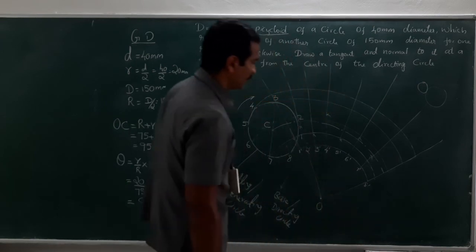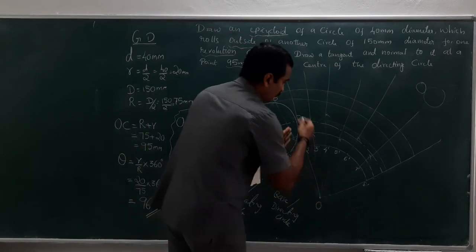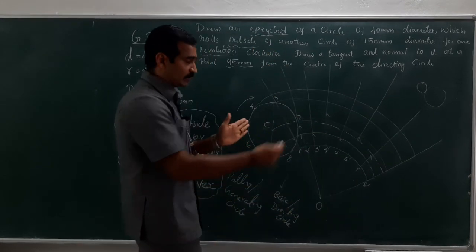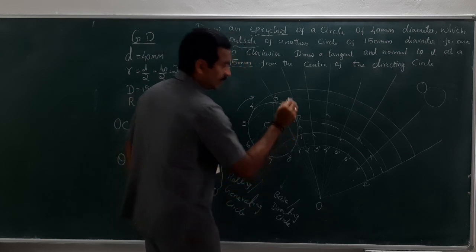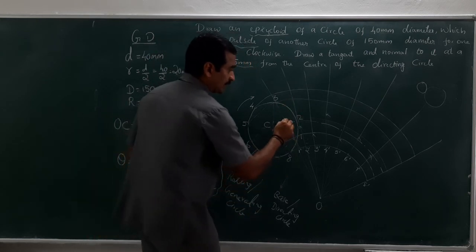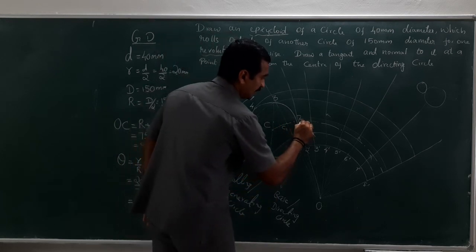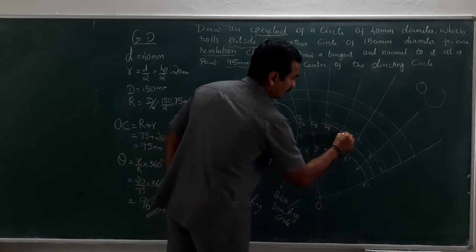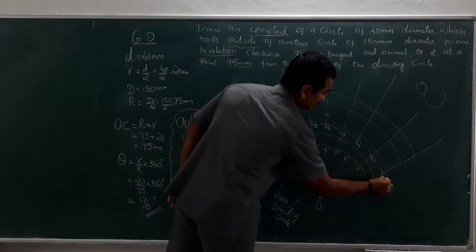Right. Now, the bifurcation which I have made, that means 8 equal divisions of the particular sector, where it is intersecting the locus of the center, I am going to take this as C1, this as C2, C3, C4, C5, C6, C7 and C8.